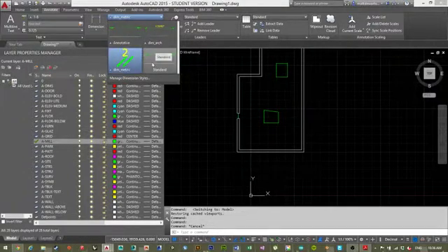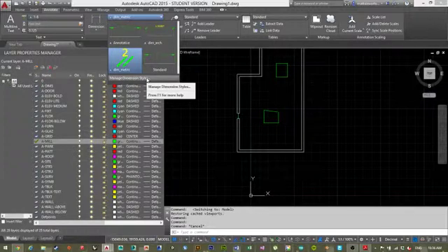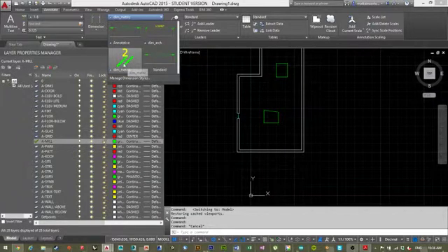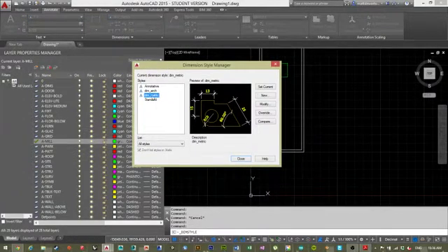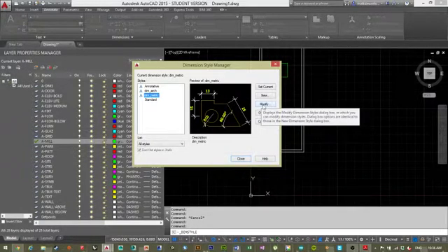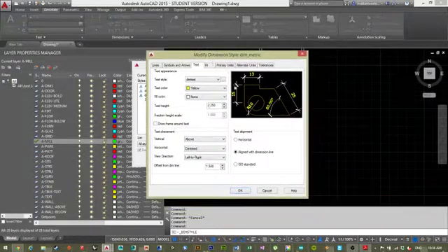All these are similar to the page style setup. People have just gone in and changed how big they want the dimensions on the page, what color they want them to be, the different styles, because there are a bunch of different styles. But I believe if you click on Manage Dimension Styles, the one that's set up right is dim metric. If you go modify, these are all the options for this. And the most important one here is really text height.